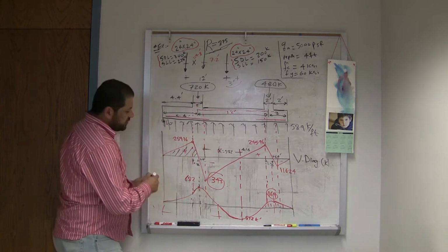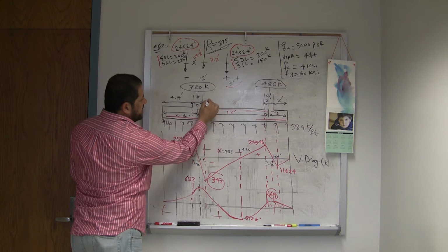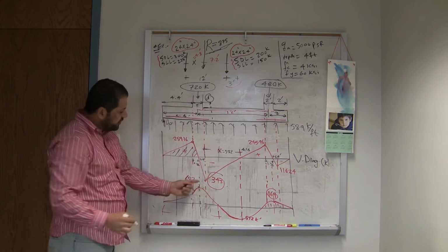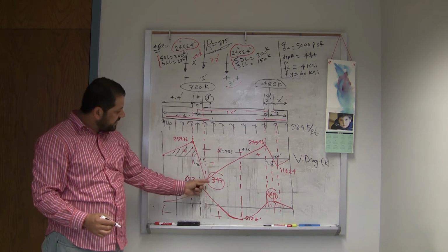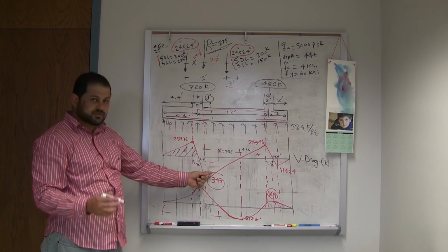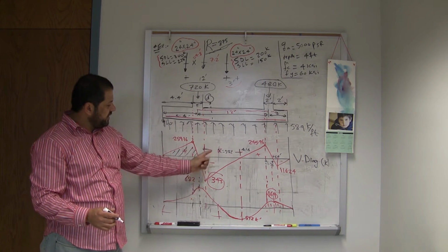The critical shear will be at D from this. So this is the face of the column. At D from here, that's the location of the critical section. We know the slope here. So if I know how much D is here, I can calculate V ultimate there, which is V bar U, as we studied. Then I can check the shear.